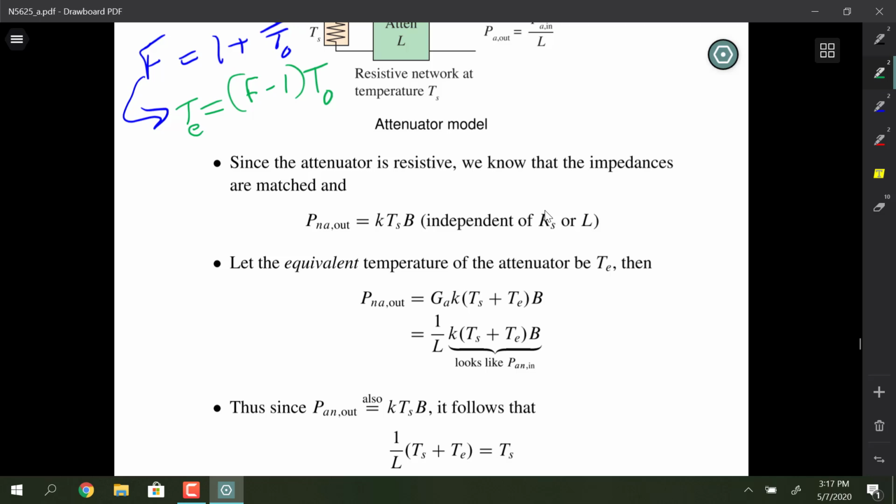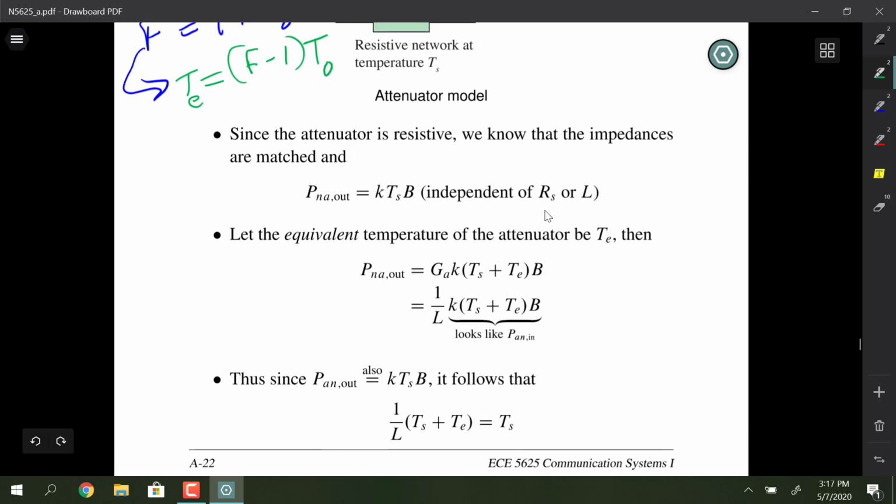Before we actually work a full-up example, we're also going to do one little investigation, and this is just to set the stage for a certain type of component known as an attenuator. The attenuator is a subsystem where you put signal into it and the signal that comes out gets attenuated or reduced in power level by whatever the attenuation value is. So if you put in 0 dBm into a 10 dB attenuator, at the output you'd measure minus 10 dBm.